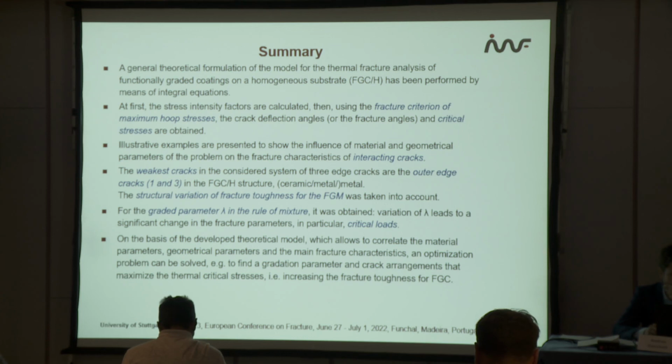On the basis of the developed theoretical model, which allows correlating the material parameters, geometrical parameters, and the main fracture characteristics, an optimization problem can be solved. For example, to find a gradation parameter and crack arrangements that maximize the thermal critical stresses, that is, increasing the fracture toughness for FG coatings, functionally graded coatings.